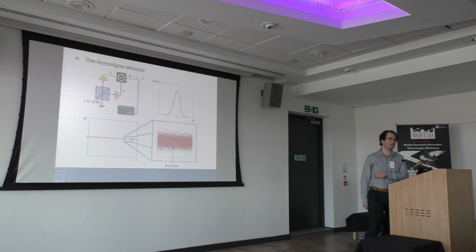between the two photocurrents of these two photodiodes, what we see is that we have a current that's essentially zero. Okay. But actually, quantum mechanics tells us something slightly different, which is that it's zero, but of course there's some distribution here. It's not exactly zero all the time. This has some distribution, and this is the shot noise.